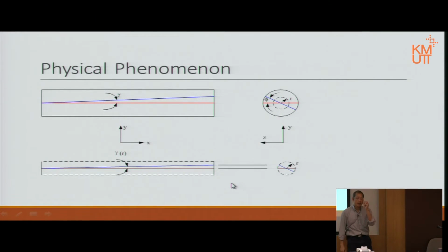Okay, so in other words, it means that the shear strain, although constant with one pair of torsion, I have to emphasize here, one pair of torsion, it's constant from the beginning to the end. However, it's a function of the radius of the cross section. Therefore, that gamma is gamma as a function of radius, whereas at the outer edge, gamma is one value, and is the maximum gamma.